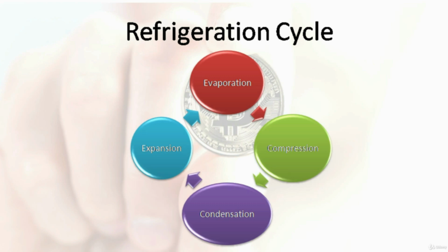Evaporation is the first phase, at which the heat is derived by the return of hot air from the space where your mining rigs are. The hot air from the space is then blown through the evaporation coil. The evaporation coil has cold liquid running into it, which, by extracting the heat from the airflow through the coil, turns this liquid into gas. The conversion to gas can happen at this relatively low temperature for a state change due to the pressure being maintained within.